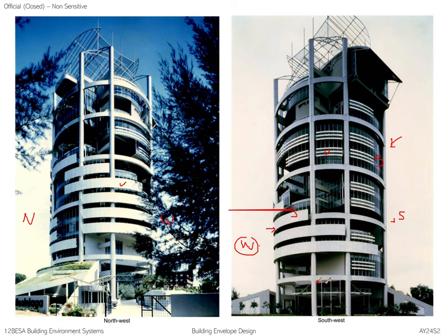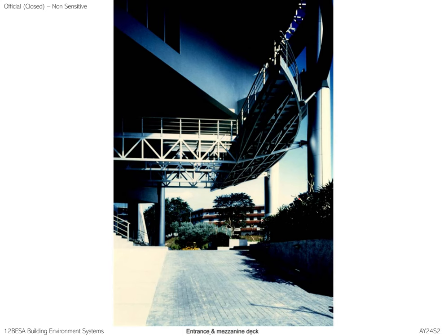Whereas at the west face, he uses these solid ribbons to take care of the first contact with the western, evening sun. For curtain wall, he still has that, but he recesses it much deeper into the space, and he uses the terrace as a mitigation device. These are some of the architectural games that are played.